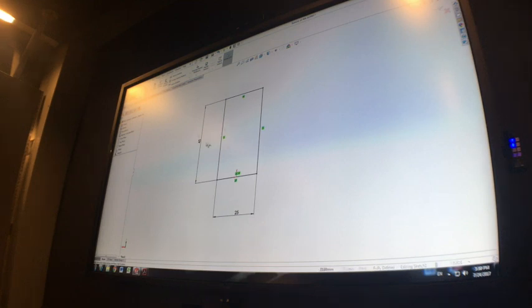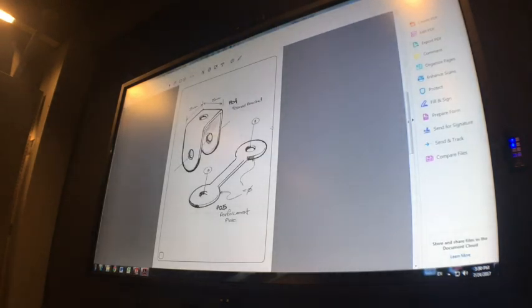All right. So that sets up the basic shape. Now, when this part goes into production, and this is looking forward quite a long way, but in project 2, we're actually going to make that form bracket out of sheet metal. So it's going to be laser cut flat and then bent. Those two sides are going to be bent on a brake press.